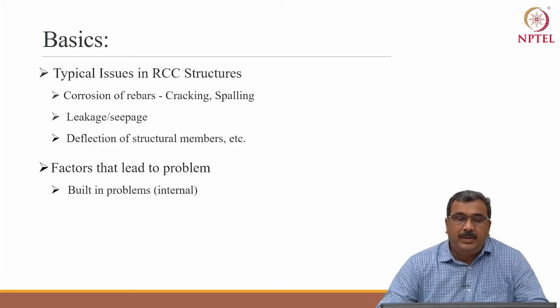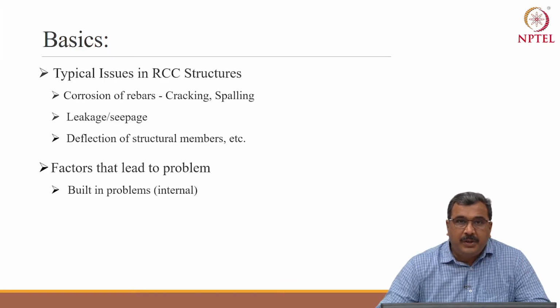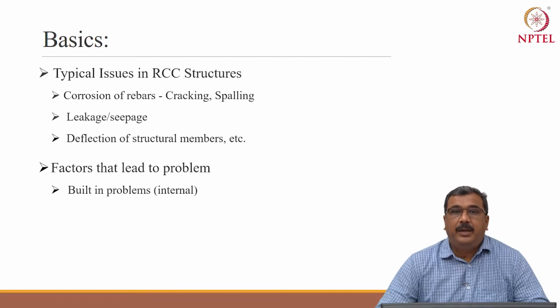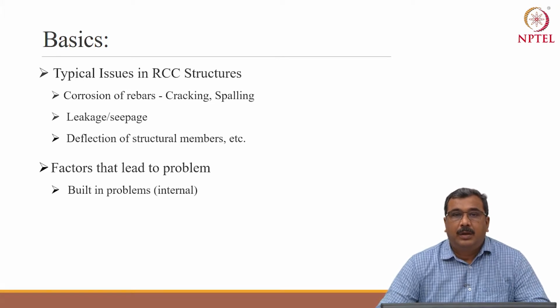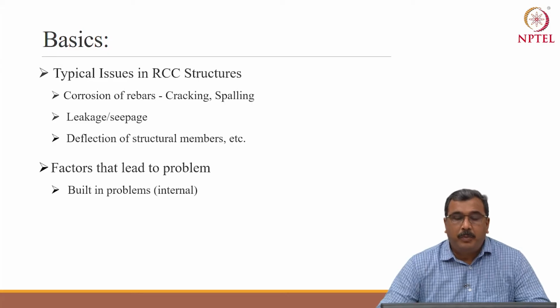Built-in problem means design fault, workmanship fault during construction, wrong selection of type of material, wrong specification of material, or waterproofing system failure, wrong specification of waterproofing.